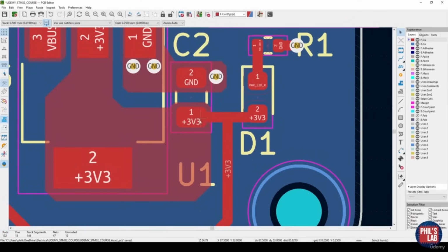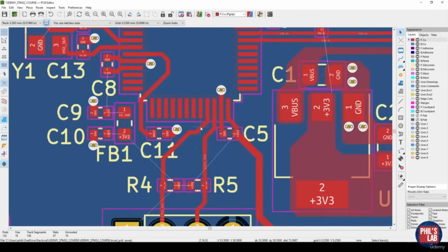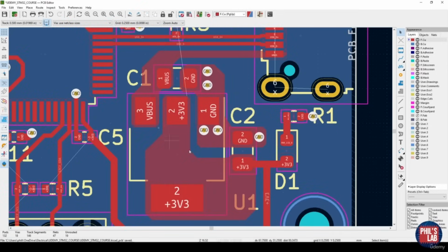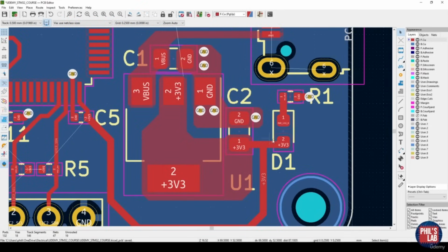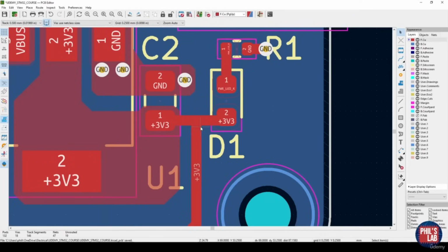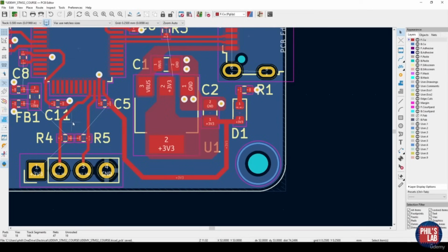So as I've shown here, from the output capacitor of my regulator, I'm going out to, for example, my LED, routing these very wide traces to various parts of my circuitry all over the board. Remember to keep clearance between power puddles, traces, and components as usual. Now, this might seem fairly thin at 0.5mm, but this can even carry up to about 2 amps or so, with only about a 10-degree temperature rise, and we're using a couple of tens or hundreds of milliamps on this board, so more than sufficient.